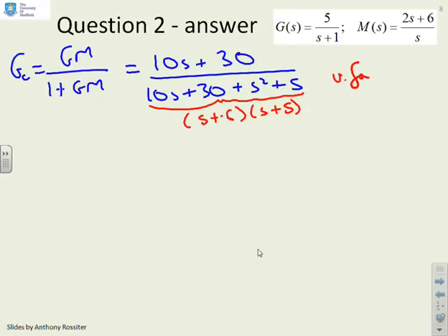So it's very fast compared to open loop. You'll see the open loop has got a pole position at -1, and now we've got pole positions -6 and -5. So we're expecting a very fast response. Now let's look and see how we achieve that.